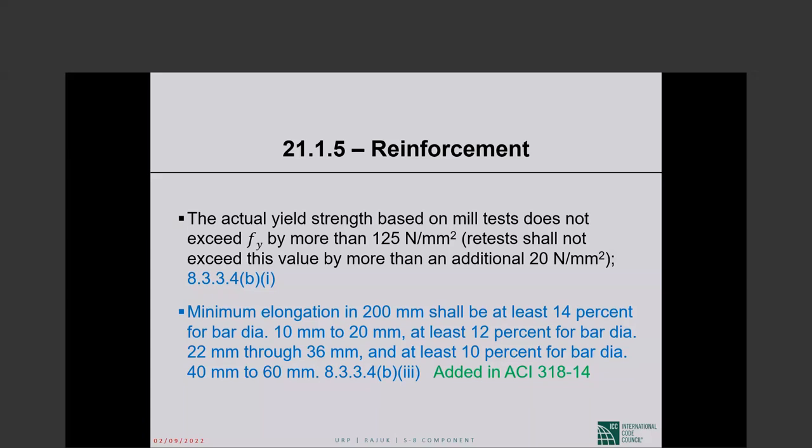They have kind of solved it now. I don't know that it is a problem. We have been very mindful of this from the beginning. Okay. So once again, if the yield strength is higher than you specify, the moment strength of your member will be higher than you bargained for. That high strength member will attract more shear force to itself in an earthquake.